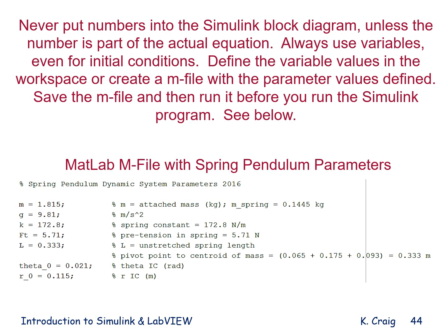If instead you just have the variable M and you want to change its value, you just have to change it in the workspace, change the value, and Simulink will read that value and then assign it to M wherever it appears in the block diagram.